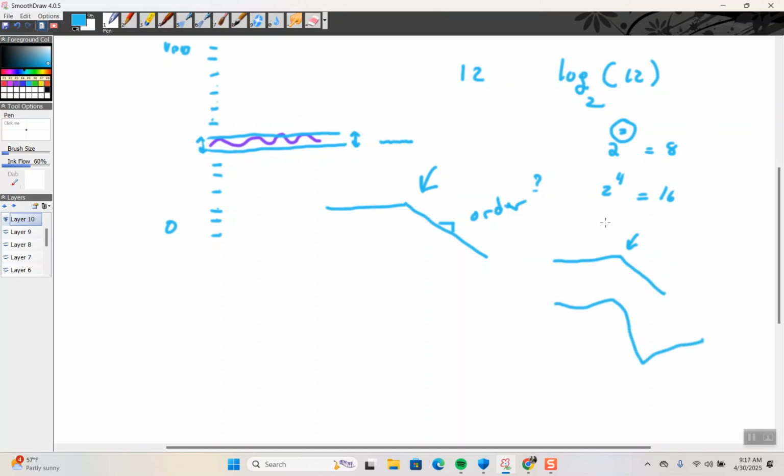There's Butterworth, elliptical, and two others, and you can use the Analog Devices wizard, and it'll tell you what it's doing. When you change the spec, it'll change what kind of filter you're using, and we're going to talk about that a little bit more later.